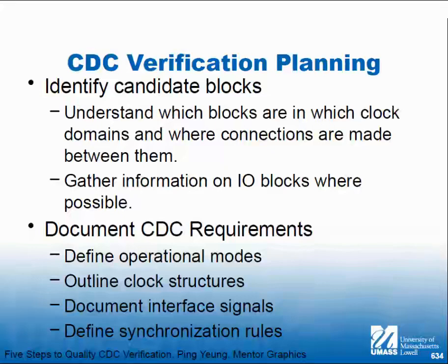So identify blocks, right? Know the boundary, and document the requirements. Like I said, make it part of the coding guidelines, especially that circuit that I keep showing, the output flip-flop to the 2 input flip-flop. And define the rules and define how it's going to be tested.